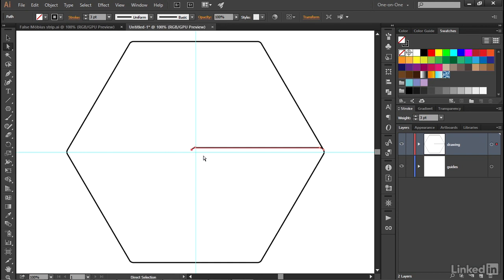All right, now press Control-0 or Command-0 on the Mac to zoom out, and then just go ahead and marquee these 2 anchor points right there and drag this endpoint, the left-hand endpoint, while pressing the Shift key, very important, so that you don't end up dragging these guys willy-nilly. You want to make sure to constrain the angle of your drag to absolutely horizontal.